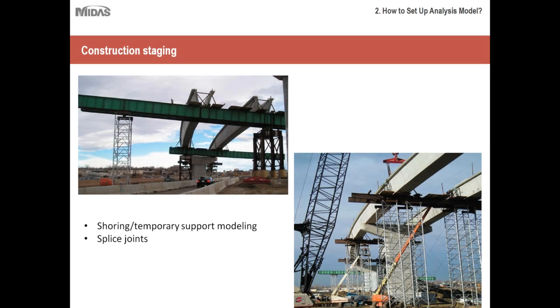So what are the challenges that engineers have to go through in this? First of all, the splice joints, their deformations and the camber are very critical to ensure the final layout of the bridge. So you have to model those supports at appropriate locations, and sometimes you have to assess the forces that are coming in the shoring member.